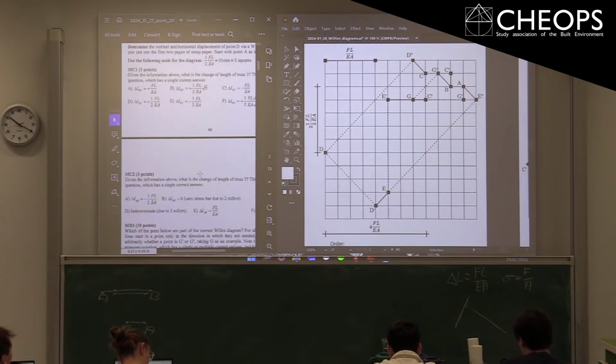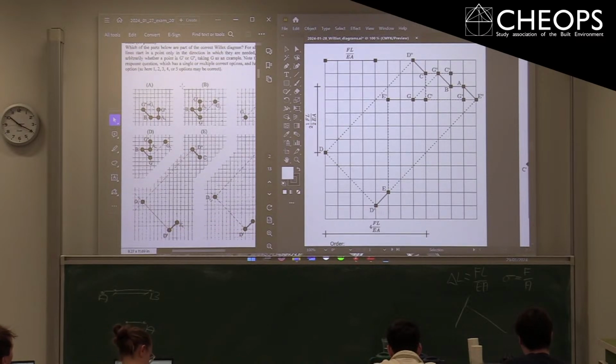Well, in these exams, they also give you these kinds of diagrams, right, over here, where they ask, okay, what is correct? And often they flip a point that needs to be in tension while it's actually correct in compression, so it needs to be at the top or the bottom. So they look very much like the one you've drawn if you did it correctly, but be aware that they often just flip the direction of one of those points to get you, well, it's not misleading, but you actually need to have the correct point.